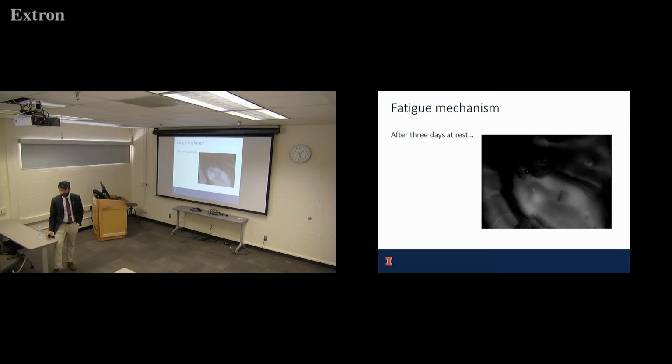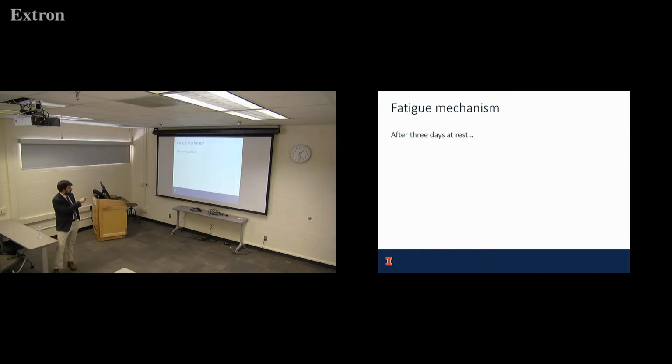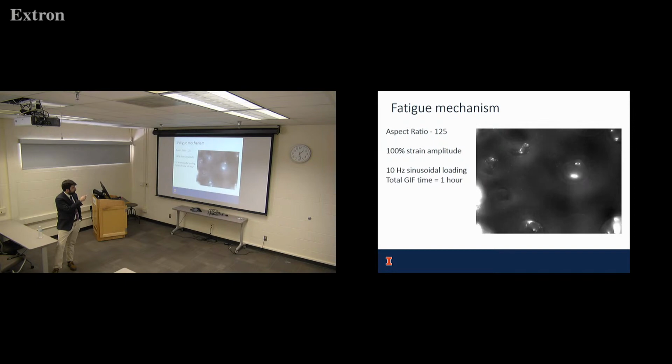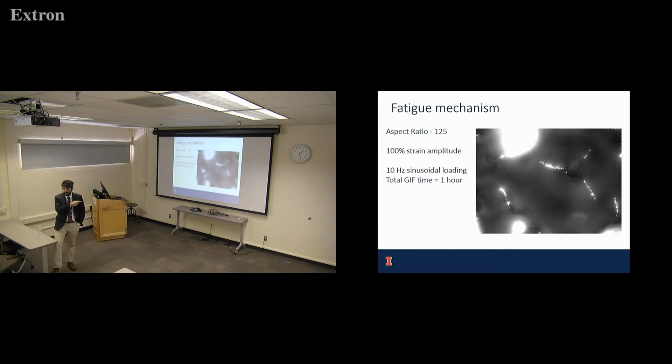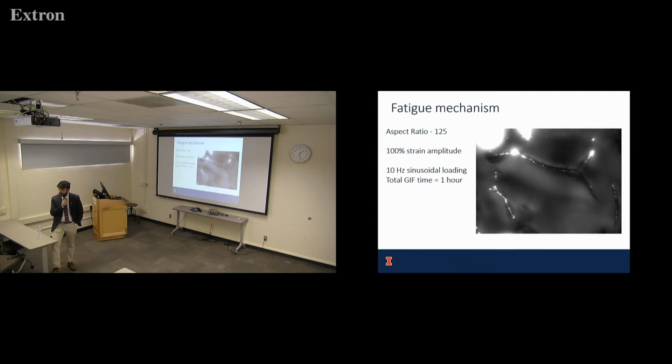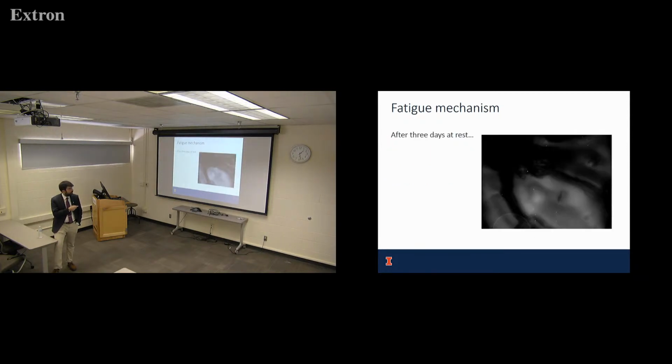You mean the fatigue cracks? Yes, the fatigue cracks. These cracks formed here after 3 days. It's the same specimen. But when you're loading it to the peak and then unloading it, you reach the plasticity. I mean, when you're unloading, you'll see the plastic damage that happened. Yeah. So why are you expecting healing whenever it reaches the plasticity? Actually, there were a couple of studies that showed this. It depends. We're talking about plastic and nonlinear, which are two different things, and it's very hard in asphalt to tell when you reach plasticity and when you reach nonlinear.